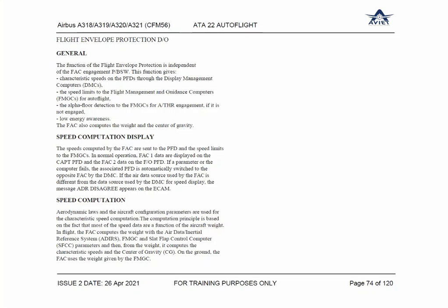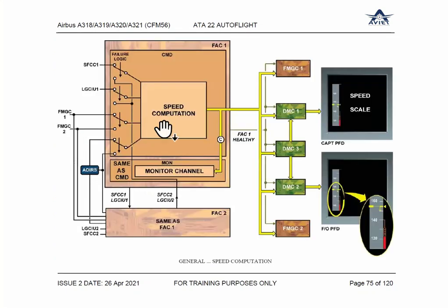Right, and subsequently the aircraft keeps on working with that weight, because the weight is continuously changing. Am I right? So the pilot will not keep the speed constant, because the weight is continuously changing. If he maintains the throttle at one point, speed will keep on increasing because the weight is reducing. You got my point? Yes. So hence the FMGC will take into account the actual weight of the aircraft and then monitor the thrust or monitor the speed. So this is how speed computation is done.